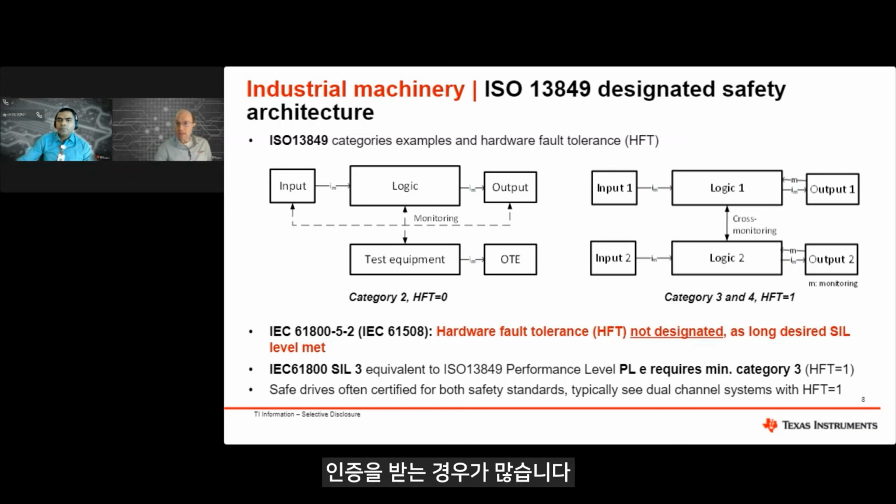Now, apart from the severity and exposure, the risk assessment in automotive takes into account the controllability of the situation by the driver. This is not considered in the industrial systems for the risk assessment. Industrial systems are typically low volume and automotive systems tend to be mass-produced. This adds additional care in the automotive development that is typically spread across multiple organizations, and the relations between the customers and suppliers could have an impact on the overall safety implications.